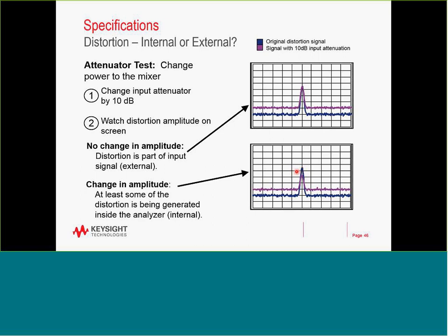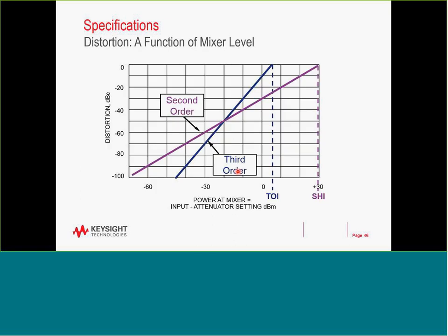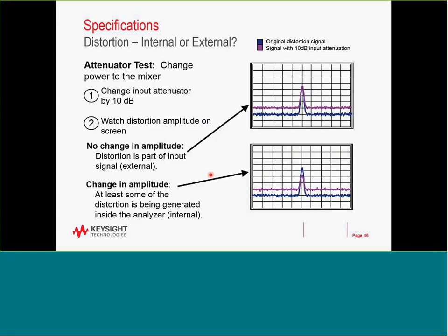So it is of interest that the spectrum analyzer has the ability to increase its attenuation in 2 dB steps. And if you increase it by 2 dB, you may find the sweet spot in between. With a 10 dB step, you might just hide the signal and not be able to find the exact sweet spot on this display. Well, let me show it here.